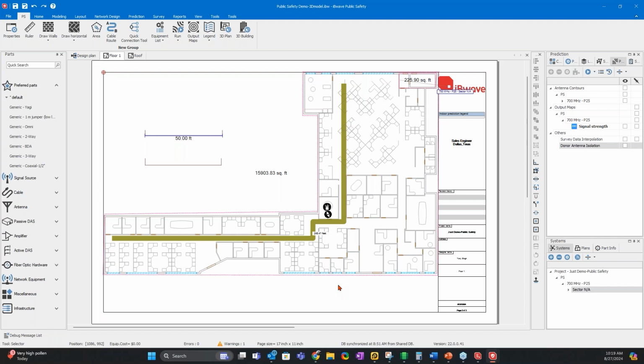hey, this is this much. One antenna can cover around 5 to 10,000 square feet. I think 3 will work. So let's use that model. 3 antennas can work in this design. So I would generate omni antennas. I'm putting 3 antennas.